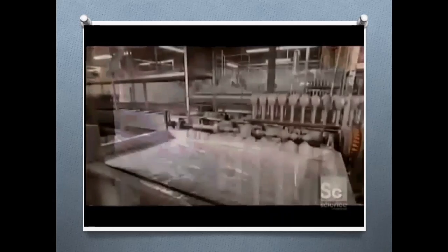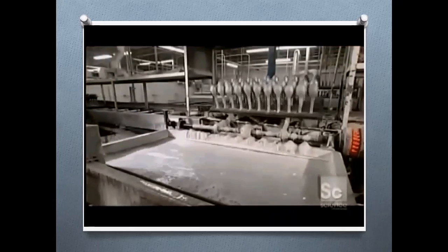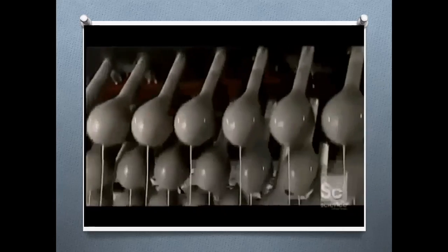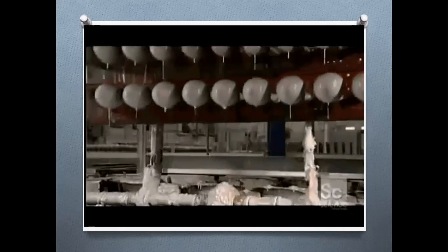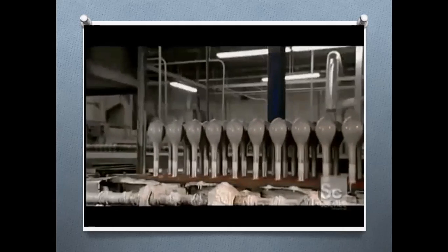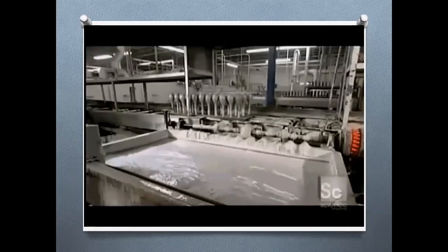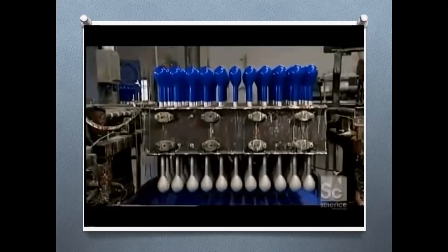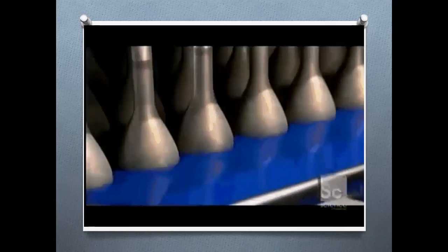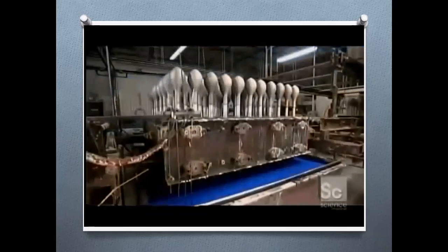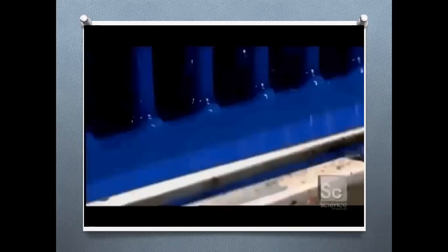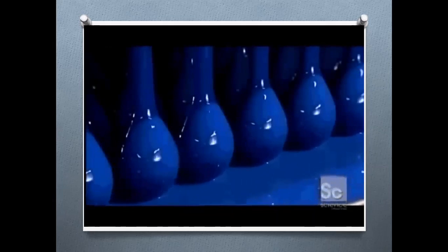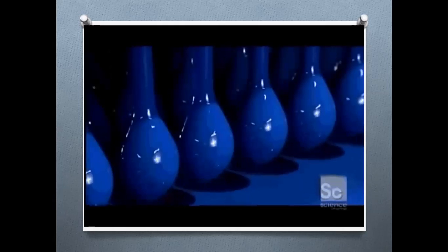You have to clean it first, and then you have to dip it into the coagulum tank. This is the coagulum tank with calcium nitrate solution, and allow the molds or forms to dry. After that, these molds will be sent to the latex tank, the compounded latex tank, and then you have to dip them into the compounded latex. As it is an industrial preparation of balloons, they are using a batch process. There are several batches of molds for ease.